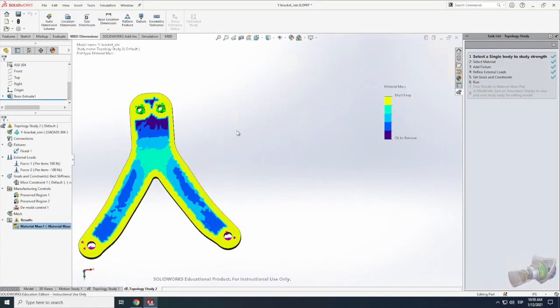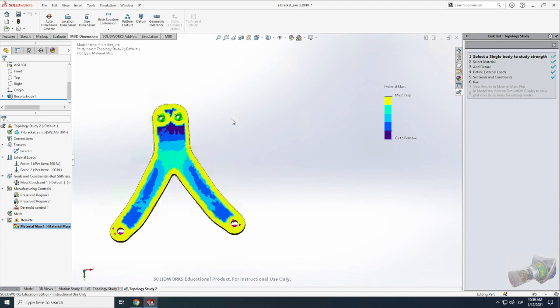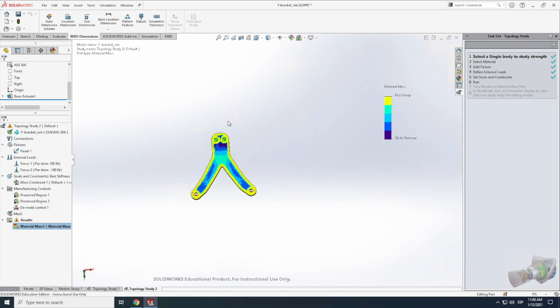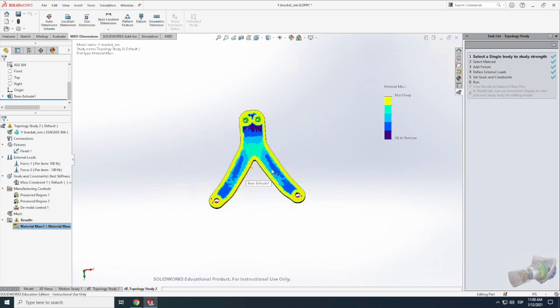All right, hi folks again. Well, it actually crashed again. I apologize for that. And after literally about an hour and so, it only did 5 iterations of what we wanted to do. And I also had to change a couple of things in here. I eliminated the minimum thickness, and the mass constraint, I made it actually 25% other than the 50 that we originally intended to, because I thought that was one of the reasons why it wouldn't start.